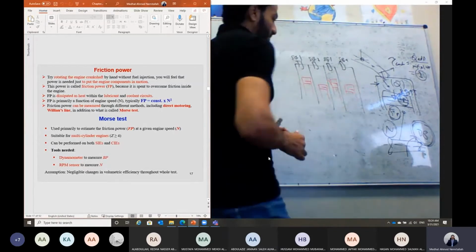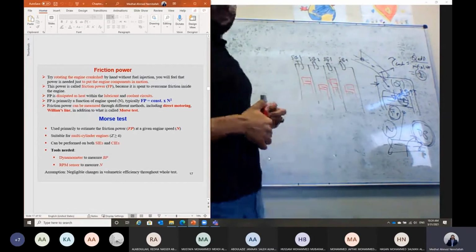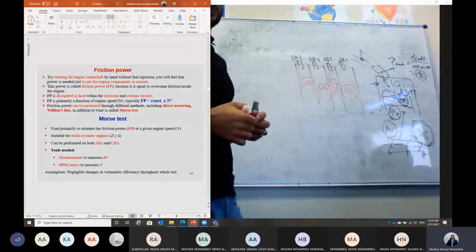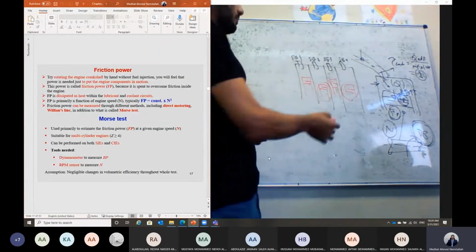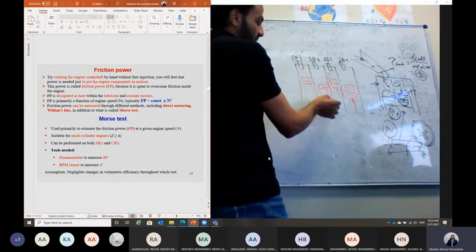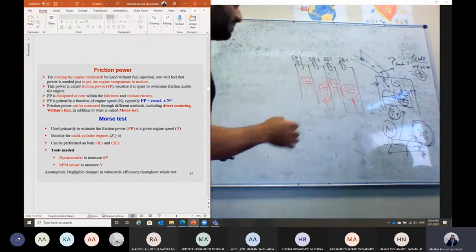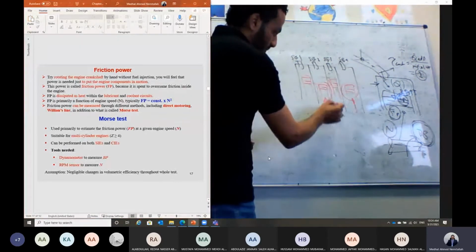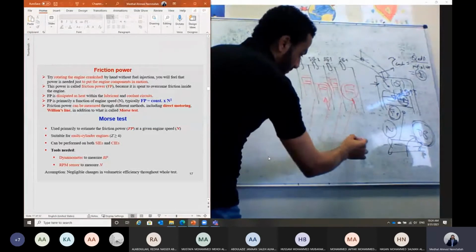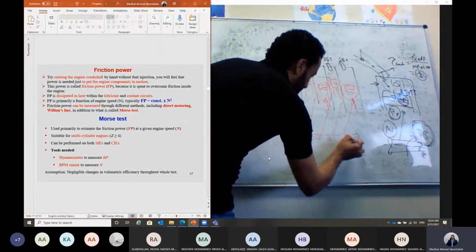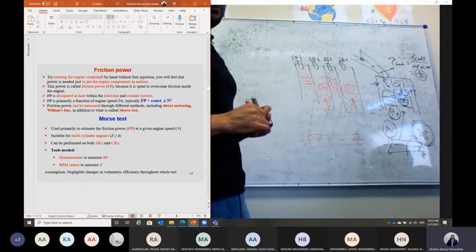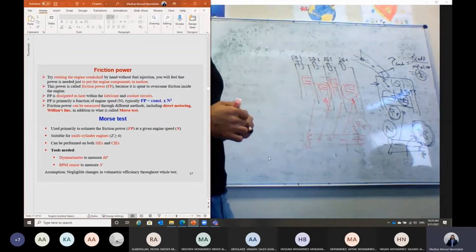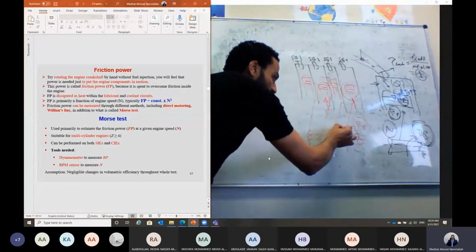Usually, if you have a 4-cylinder engine, two cylinders move with each other, but they are doing different strokes. So one here should be doing the exhaust stroke, and this one will be going out during the compression stroke. But they are moving together, and the other two are moving together. All of them are connected to the crankshaft, in order to reduce the stresses applied on the crankshaft and create a kind of balance. Those are the connecting rods, and at the end we have the brake power at the output crankshaft, which should be running at a given RPM.